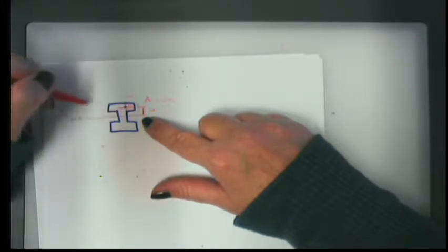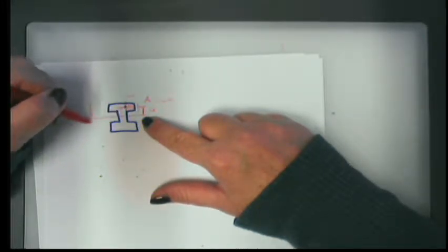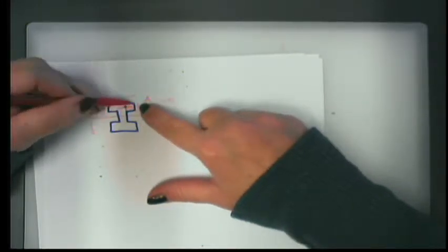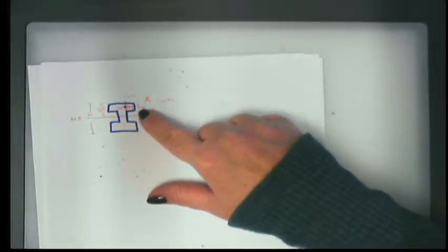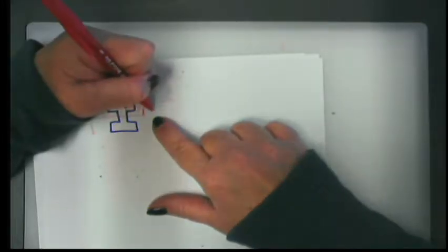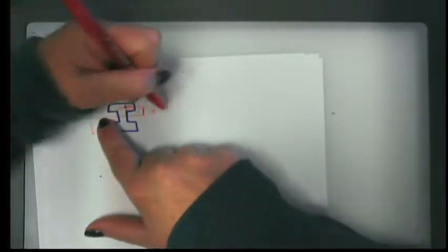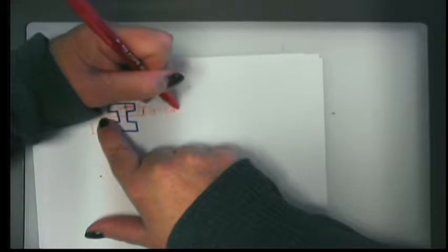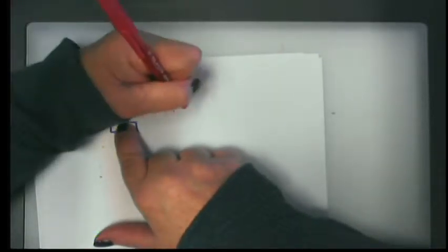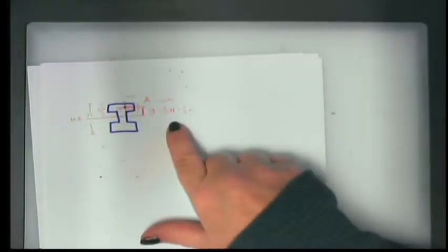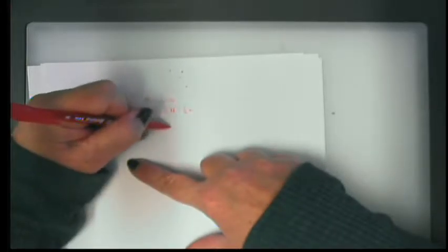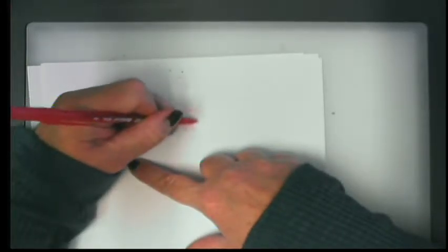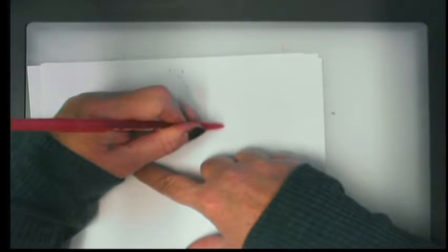So this is going to be, if this was capital H, the height of the whole I-beam, this would be half of H. And this little chunk right here, my centroid here, is half of little h. So my Y bar is going to be half of big H minus half of little h. And so my Q is just WH times 1/2 big H minus 1/2 little h.